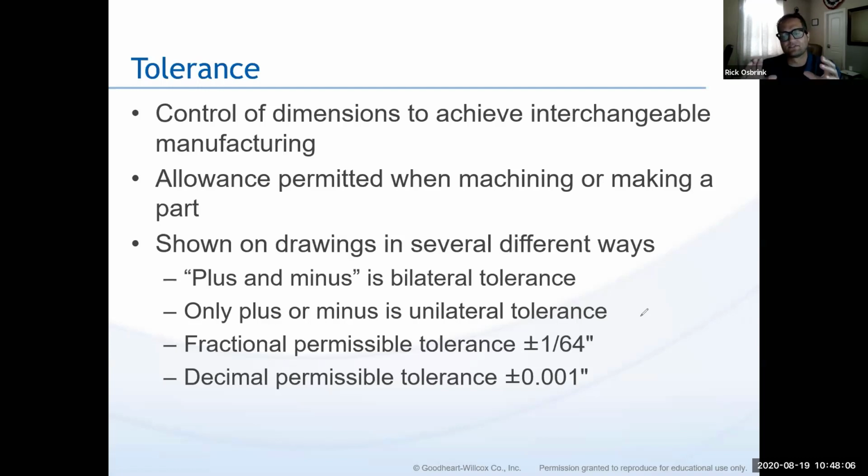So I need to be able to look at this and say, hey, this is a crucial measurement. I need to give him that one. This one maybe not a crucial measurement. He can determine that measurement based off of these other measurements and just leave that off the plan. That way the plan is a little bit cleaner. It's easier to read. There's not so many crossing lines and measurements and stuff that are going to make my eyes go cross. So one way that I can do this is you saw me noting a diameter of 500